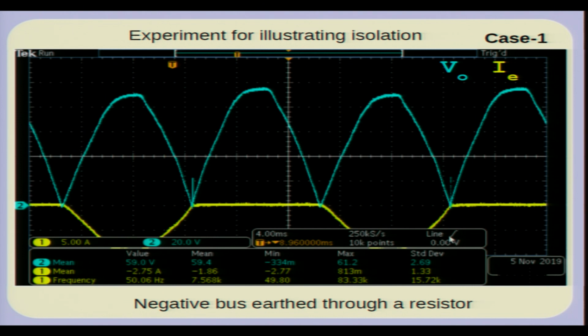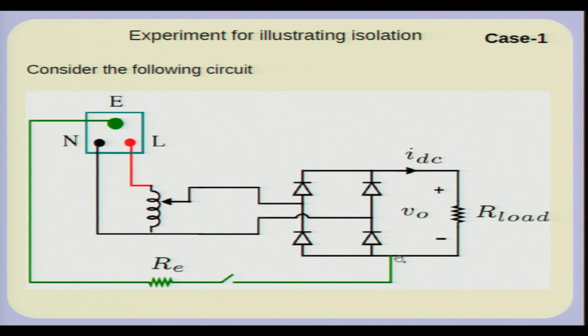So, the point is that in this circuit you cannot connect this point arbitrarily to the earth. This is an important point. Why does this happen? Is there a return path? The answer is yes. This current flows here, goes into the earth, but in most of our 3-phase power supply systems, remember the single phase supply is derived from a 3-phase supply, and at least in a laboratory the 3-phase power supply coming from the utility is grounded at the source point, the neutral is grounded. So the current will flow and enter the earth and come in the earth conductor and get connected to the neutral somewhere near the source. So, depending on the nature of the 3-phase connections and earth connections, there is indeed a connection between the neutral and earth.